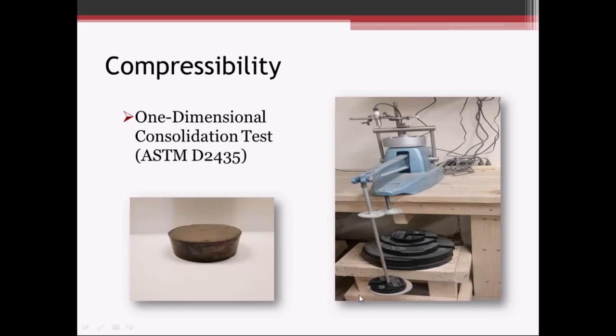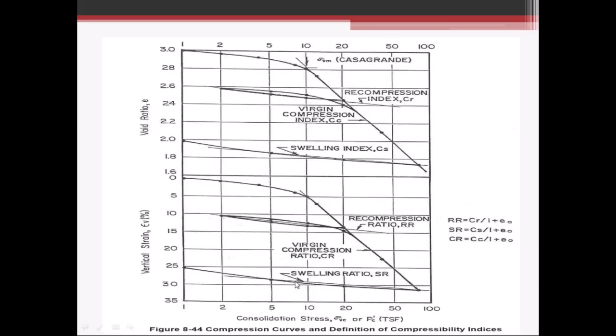So then the other thing I want to point out here is the engineer really needs to determine the location for this test. So if there's a 30-foot clay layer that's being evaluated from this test, only about 3/4 of an inch of that is being tested. So the engineer is the one that needs to determine how many intervals, how many locations to perform.